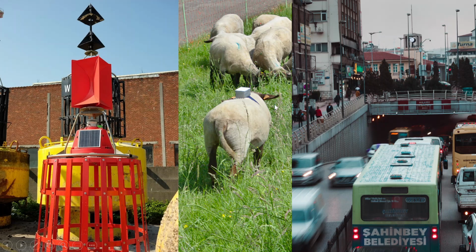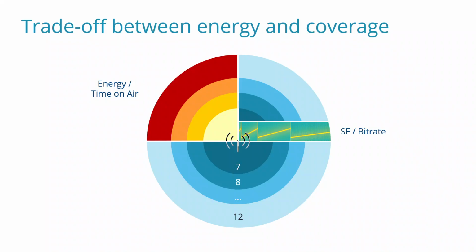And in the other project, in the middle, we monitor some vital signs of sheep. While they are confined to one area, sheep tend to move around, thereby introducing some dynamics in the channel. To be able to adapt to different propagation conditions, LoRaWAN, the protocol under investigation, changes its data rate. Decreasing the data rate ensures that the signal has more energy per bit, and therefore the signal can reach further. This is done by changing the spreading factor.